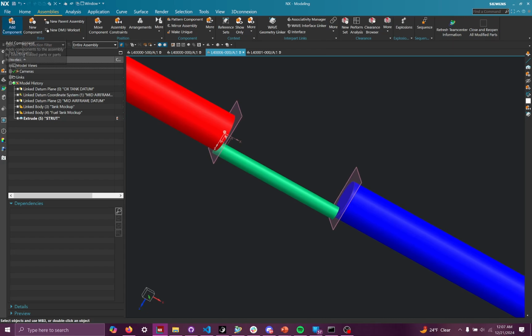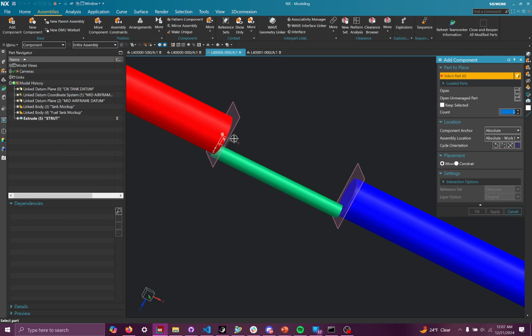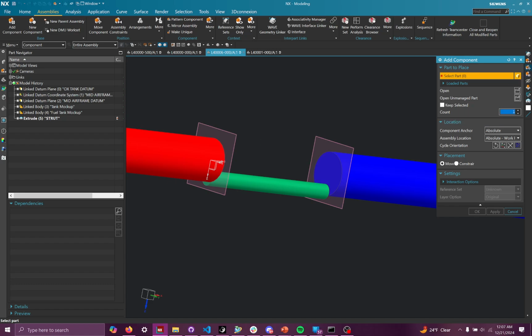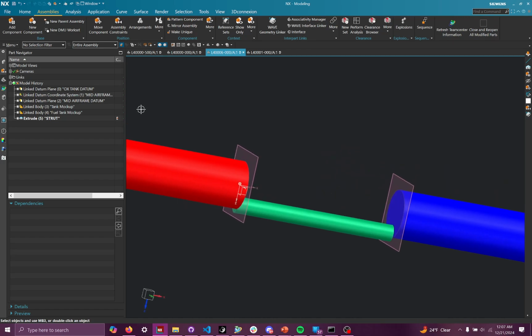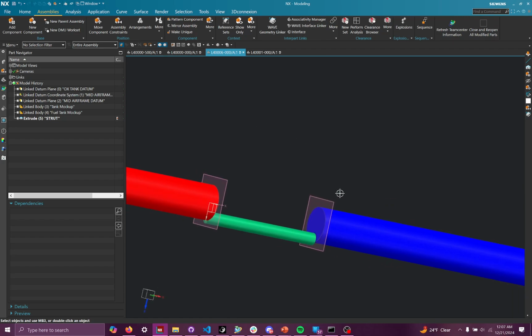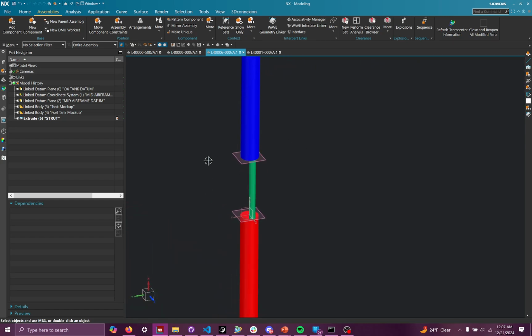And you do that via add component, and then you add the assembly file containing the geometry that you want to include, and then you wave geometry link that body within the assembly file. Hopefully that makes sense. That's a lot of very similar sounding words stacked up.